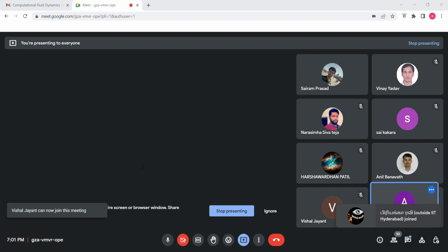Since we are using only this value, the rest goes as truncation error, and we denote it as order of delta x. So basically all these terms we denote over there. The truncation error is proportional to the kth power. That is what we mean by order of the equation. That is, the order of the discretized equation is k. It means that the truncation error is proportional to the kth power. Here, the order is proportional to delta x.